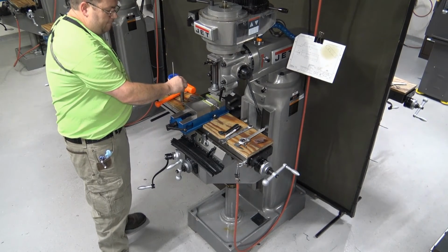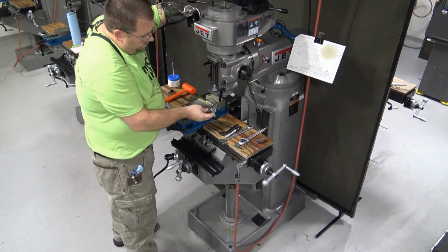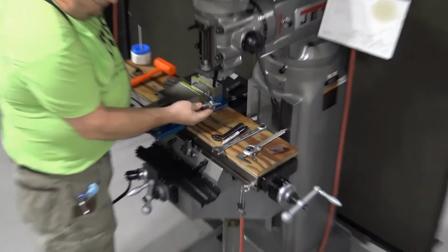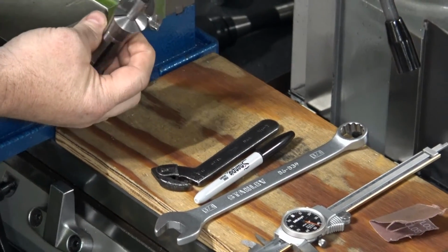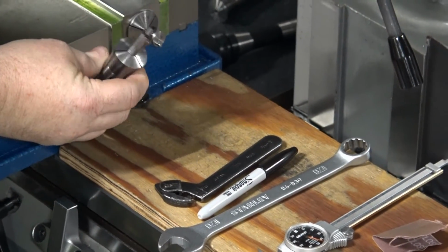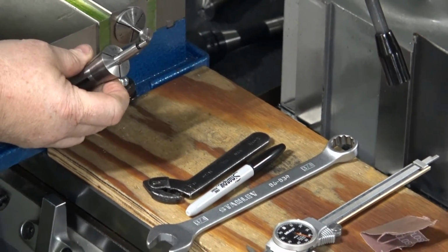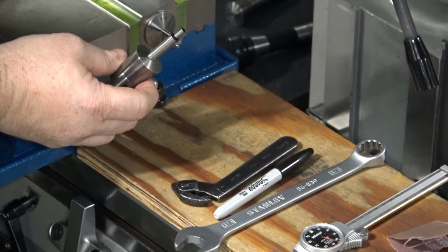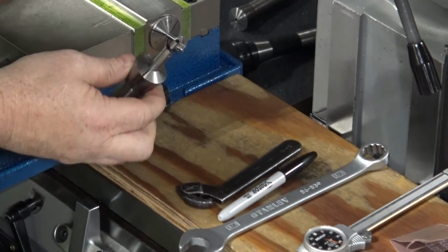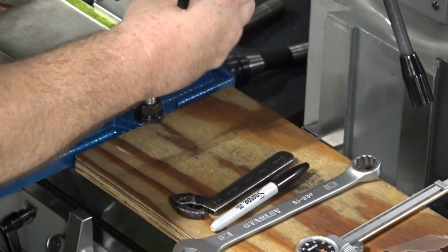Okay, so now that I have my collet gathered up, remember this is an R8 collet because that's the one that goes up in the spindle of the milling machine. We have a 3/8 size collet because what I like to do for finding position of that slot in my crankshaft is do an edge finding operation from the front face of my crankshaft. Let's go ahead and put our collet up in.